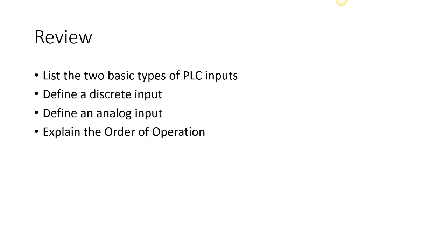So just so we understand how the PLC operates is going to help us understand how to troubleshoot our PLC programs. If we get something out of order inside the program, it's really going to cause problems. And sometimes all we have to do is change the order in which our program is written, and it's going to solve a lot of troubleshooting problems that we can come up with.